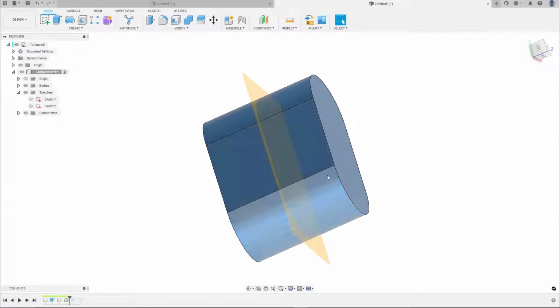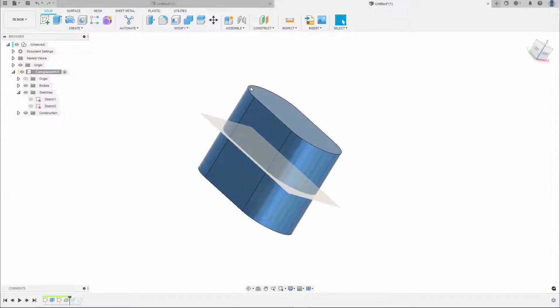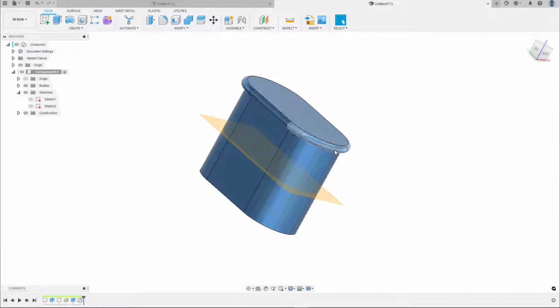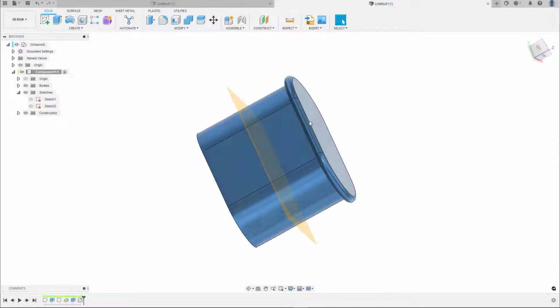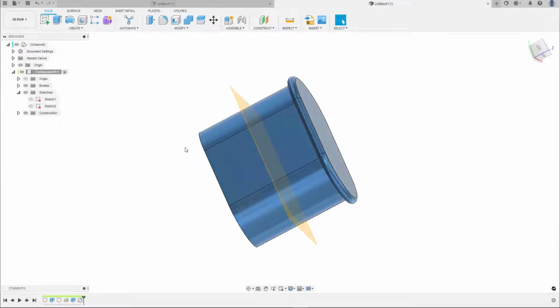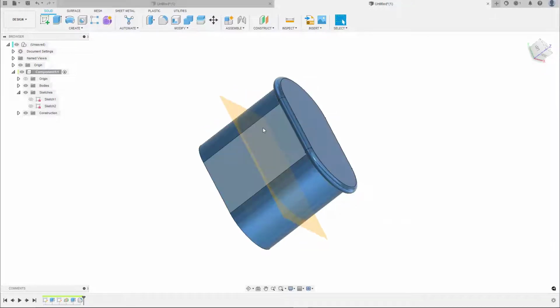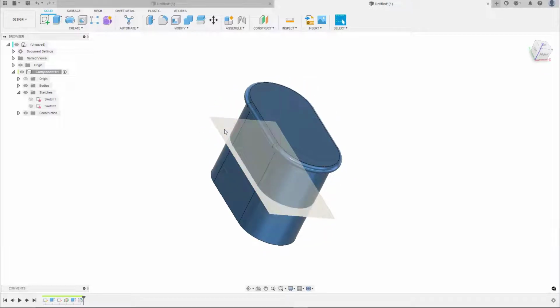So whatever the amount of extrude you put, the plane is always going to be in the center, which means when I go in the timeline, add this part, and say this part has got to be mirrored on the other side, every modification is gonna follow. We won't have the cap hanging in midair because you changed the extrude. So that's the good way to do it, basically. One way to do it, because there's so many ways to do stuff in Fusion 360.